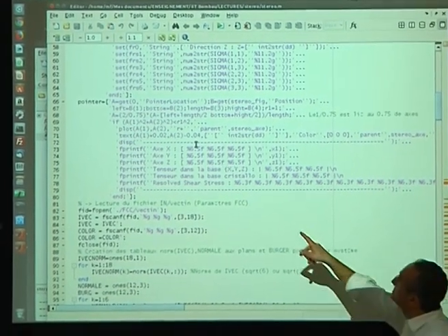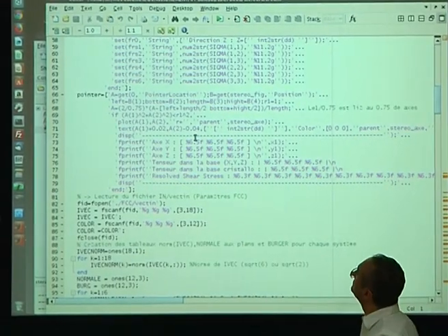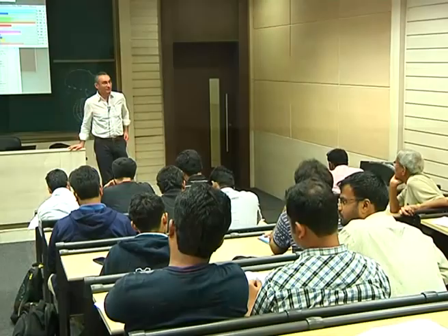You see, this is done by this thing, the subroutine that gives it for you. So the summary of this study was, if you want to use crystal plasticity with a dislocation density based model, you can fit the parameters using dislocation dynamics with dedicated experiments that you specify. This will give you all the isotropic coefficients very nicely. For the kinematic hardening coefficient, this has to be done for each purpose, because there is no, today at least, there is no kinematic hardening rule available yet. There is one for fatigue. I gave you the references. And you may find some for the crystal shape also. And I'm not aware of some for precipitates, although there are. And that's it. Okay, so did you want to say more words?